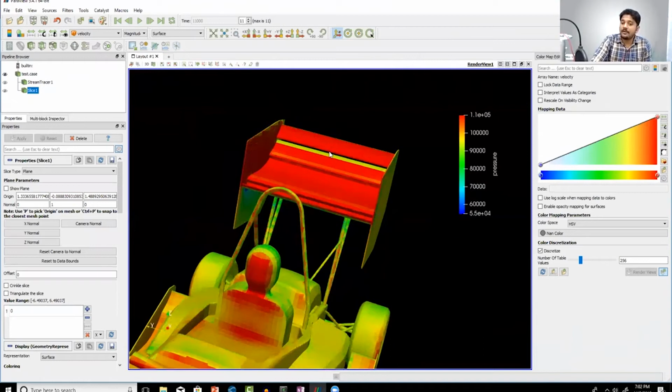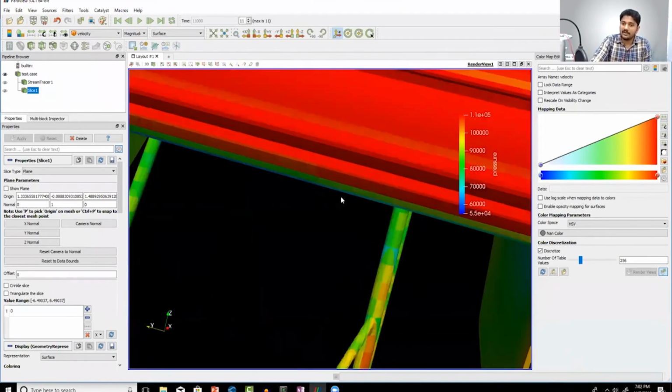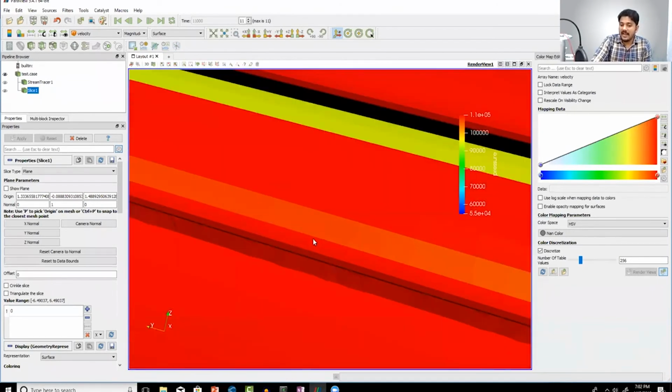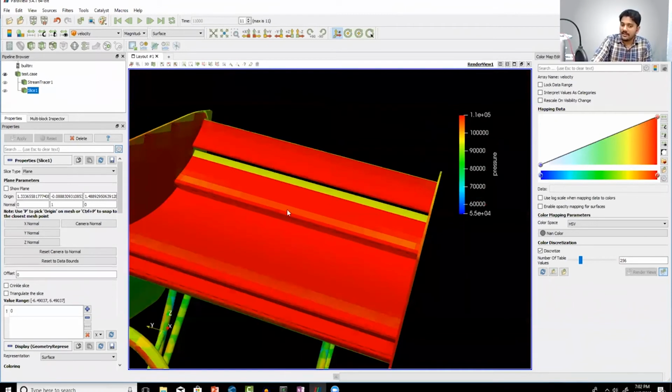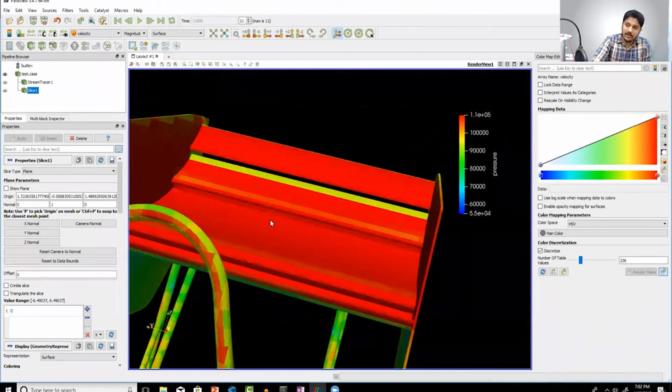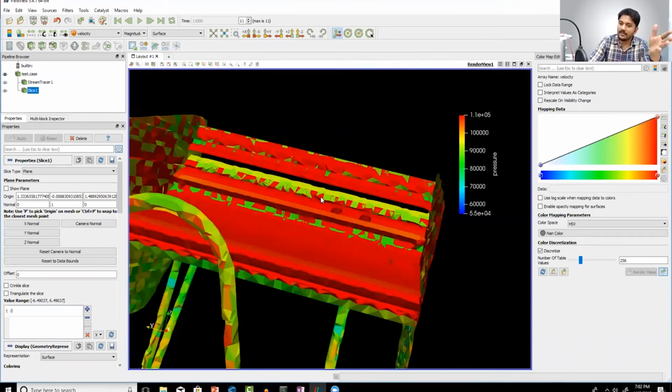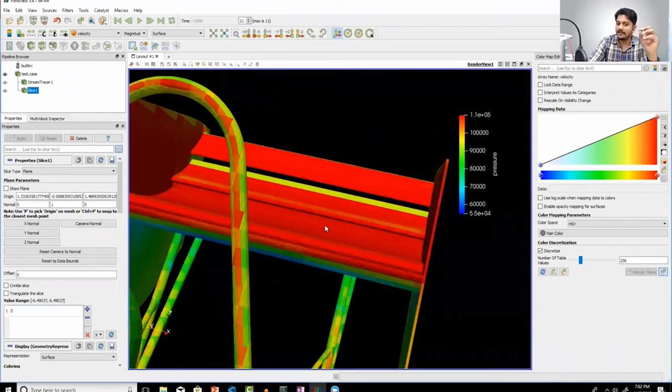The gap between 2 consecutive wings is very, very important. Now in this case, you can see that the gap between the second and third wing has actually been shut down. So this simulation is wrong, right? But since it's a made up model, you can showcase these defects. Whenever some students send out their simulation results to me for consulting, when I look at them, they make these types of mistakes. If you're making these mistakes, then that's going to give you completely bad results, right?